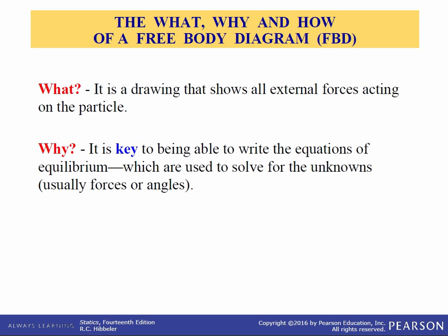So what is a free body diagram? It's a drawing that shows all external forces acting on the particle. And we can also say it's acting on the rigid body, but we'll get to that later on in the course. Why do you want to do it? It's key. That's why you must be able to write the equations of equilibrium and use those to solve for the unknowns, which are usually forces or angles.